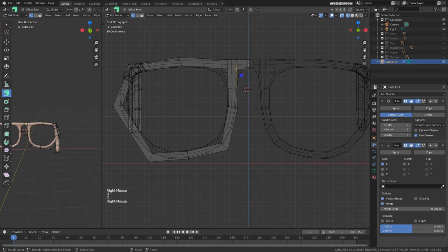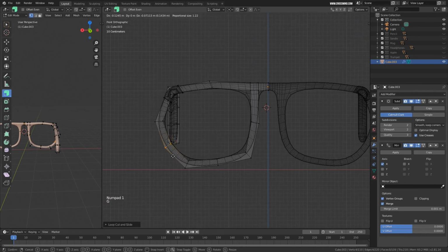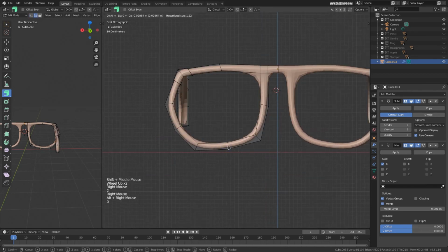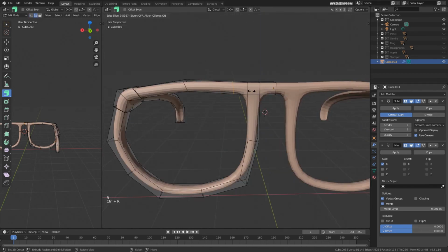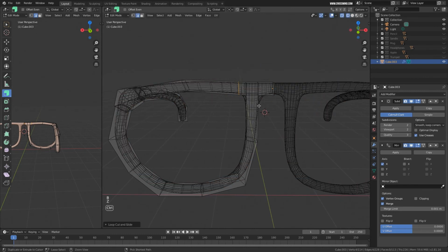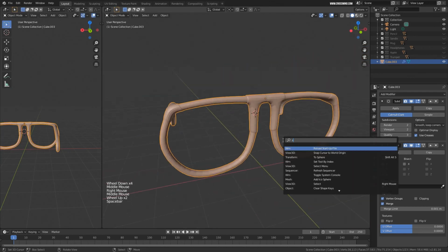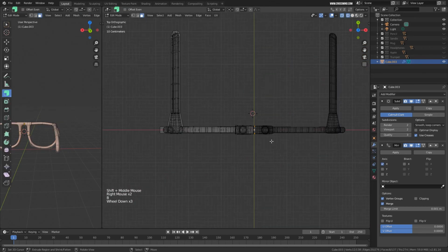And if you want, you can make more adjustments and maybe bring a loop cut over here and make this one smooth. Maybe bring a loop cut and make this one sharp, and you can select all these faces. Like this one, you can extrude along normal 2 times to give it some thickness. Okay, shade smooth. I'll select these, and I can switch on the proportional editing.